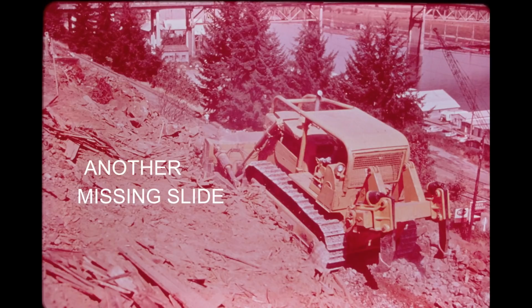The pad ends of the diagonal braces are mounted with bushings and clamps to the center of the pivot shaft on the 9B and to the inboard ends of the two pivot shafts on the 25B and C, as shown here. The main cases on these units are fabricated to expose the pivot shafts and to provide clearance for the clamps used to secure the braces to the shaft. These braces provide additional stability for the undercarriage and also serve as an additional pivot point for the track frame oscillation.